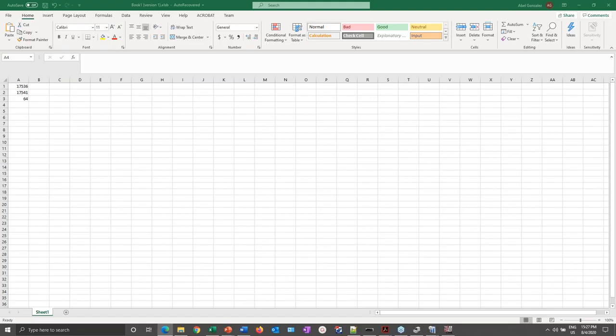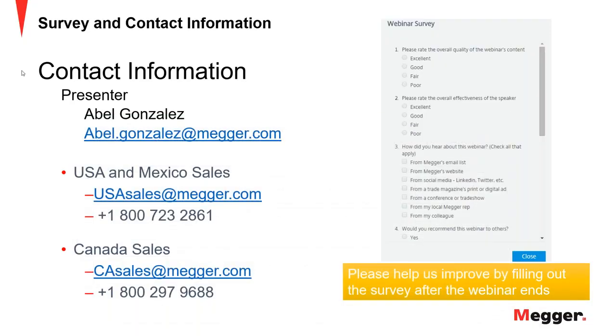The thing is that when you read the settings from the relay, it's going to give you whatever the active group is at that point in time, and that will technically be the relay settings that you test on. If you need to change to an alternate group, group 2 or 1 through 6, however many groups the actual relay has, then each group can be classified as a relay. So you would read group 1, test your relay, and then save that information and result and template off. Your second group is the same relay, just a second group, because all the settings are still available to you in that second group. You just have to classify it as group 2 of the same relay, and so forth until you complete all the groups that you need tested.